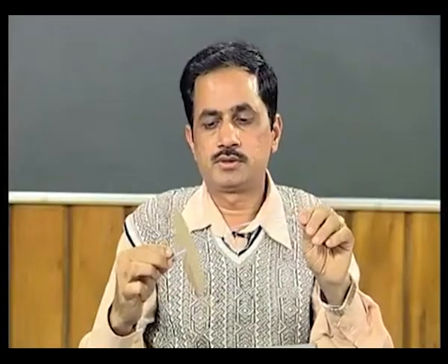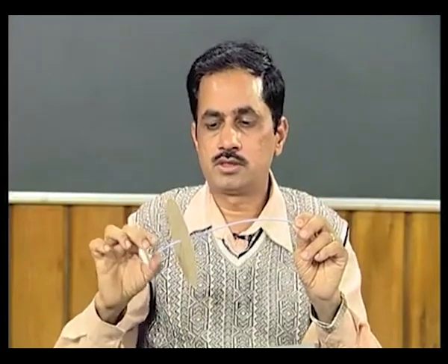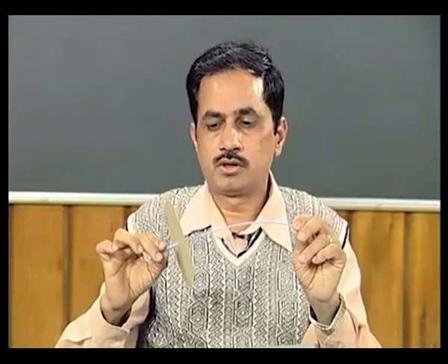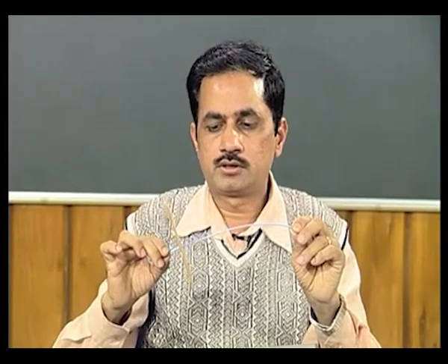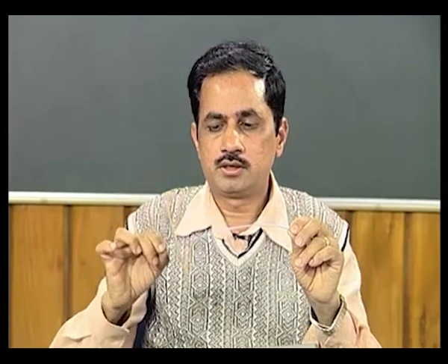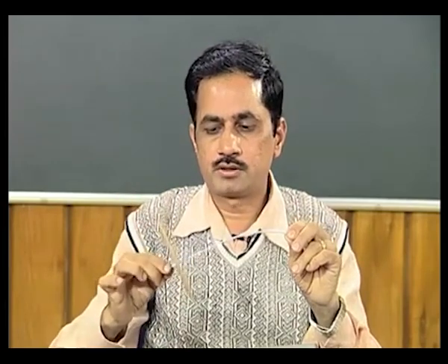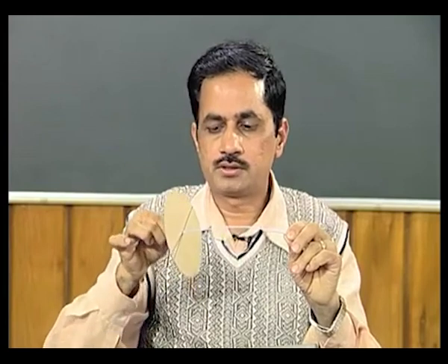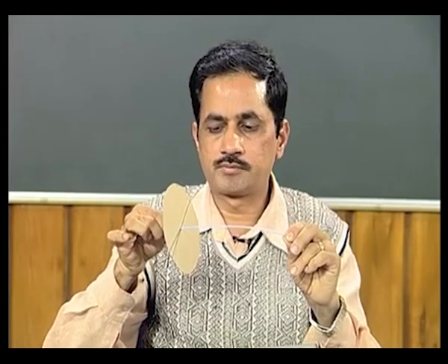So, in this particular case, let us visualize the motion of the disc. It is not spinning, only the whirling we are considering. So, this is at the bottommost position. Now, if I consider the motion of the disc during whirling, you will see that earlier you could see only a line of the disc, but when it is whirling inside towards me, you can see the inside face of the disc.